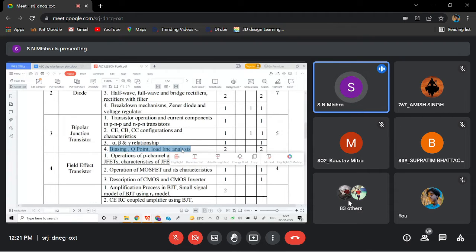Biasing is nothing but applying the voltage to the transistor amplifier circuit and properly choosing the resistance, capacitance, and the other components present in that amplifier. How we choose those, so that the amplification purpose will be fulfilled. As a designer, when you design, everything should be fixed in the perfect place. The component values, supply voltage, everything should be fixed depending upon your requirement.